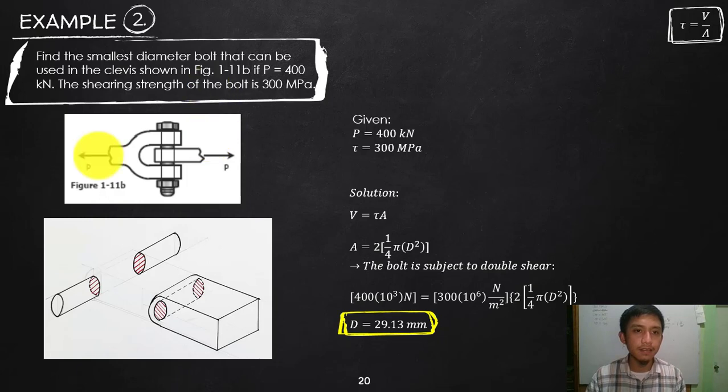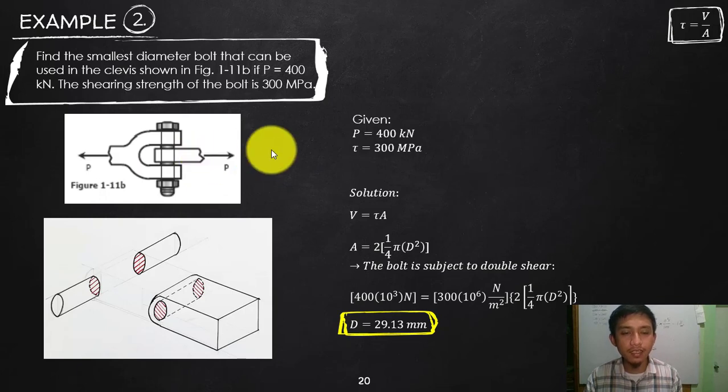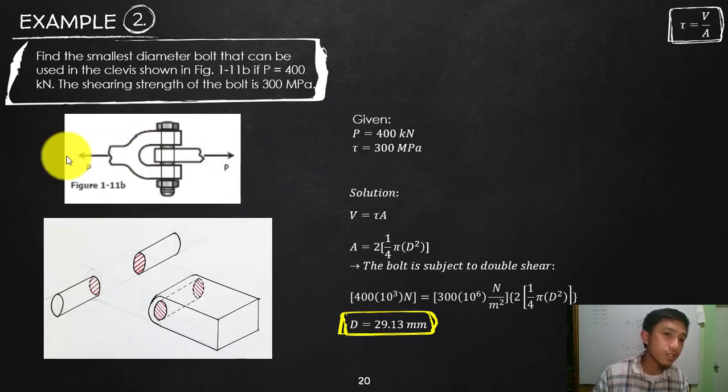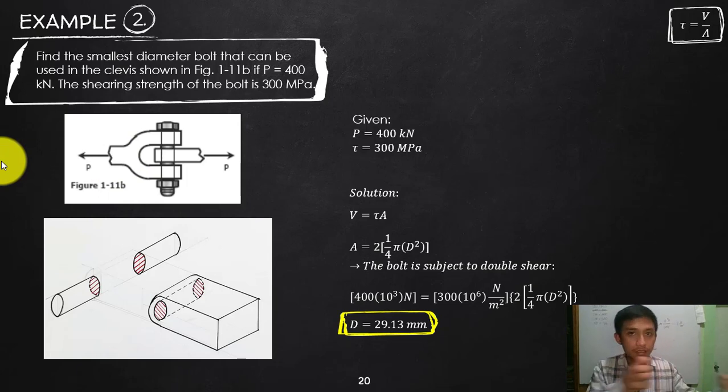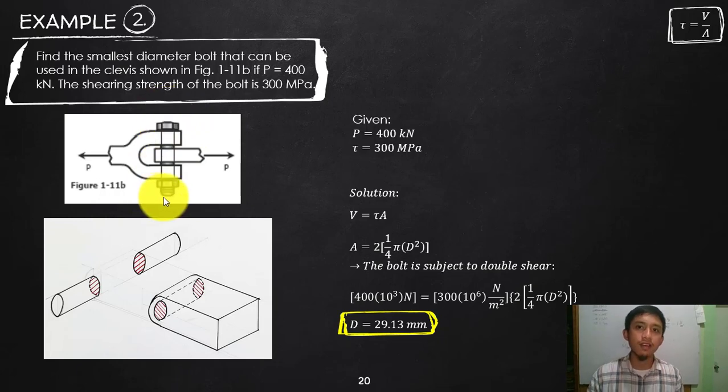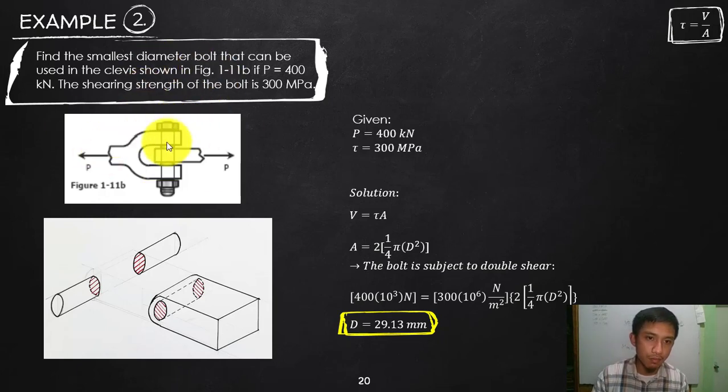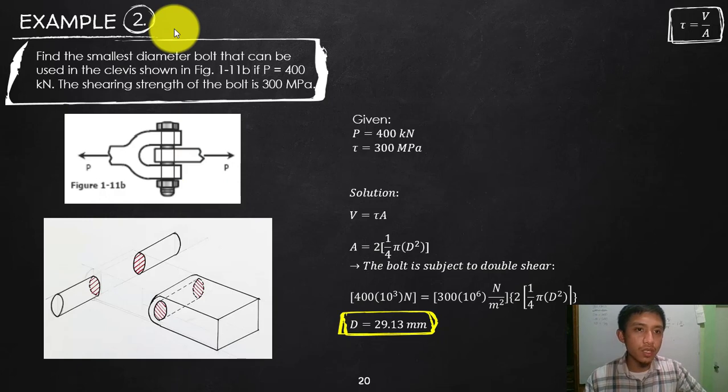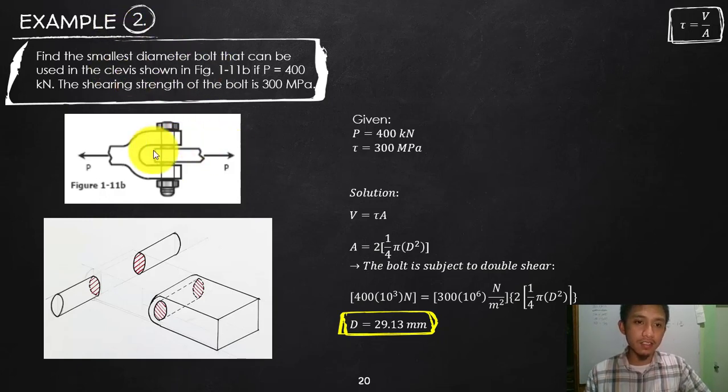So the question there is, if you apply a force P in this part of the socket, that will also be the same force that will be experienced on this side, because again, equilibrium. So this force P is trying now to destroy this connection, but that connection is being retained because of the bolt. So the stress is actually carried by the bolt. Now the question, why is it that it is under shear? Let's try to analyze. Why is it not normal? So what we are trying to figure out here is the bolt, guys.